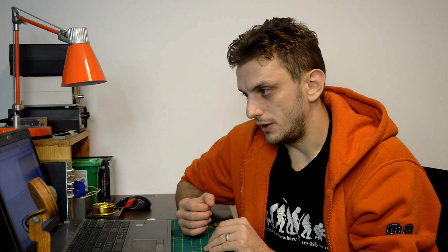And that's the thing about creating models for any sort of component. You'd basically need three very important things to create a good model. So first of all, you need to have a very good understanding of how the component works. So what does the component do, and how is it operating from an academic point of view? So what are all the parameters that have to do with that component? Secondly, you need a datasheet for the component, since only the manufacturer knows what he did there, so how did he make his component? And thirdly, you need the component itself.